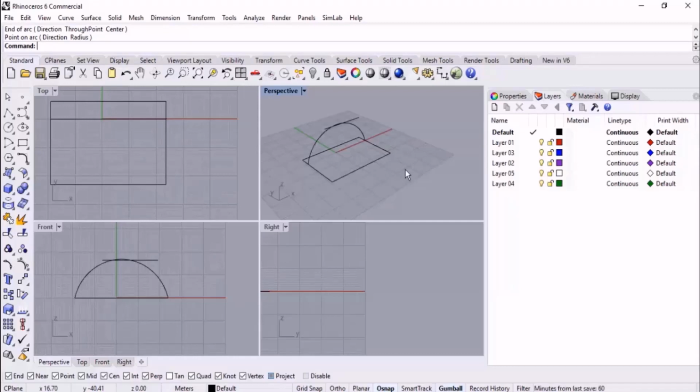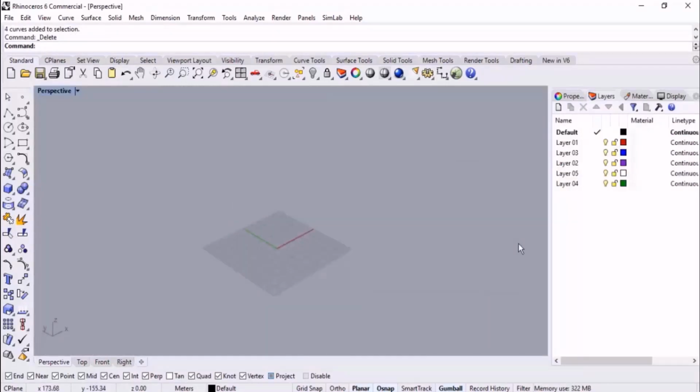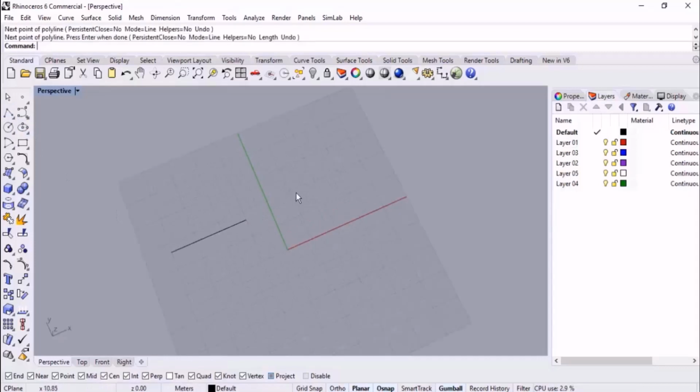If I disable planar and use project individually, all of the curves or drawings will be projected on the origin point by neutralizing the effect of snap objects, which is not that frequently used. In the continuation, I'm gonna give you another example and then finish the topic.